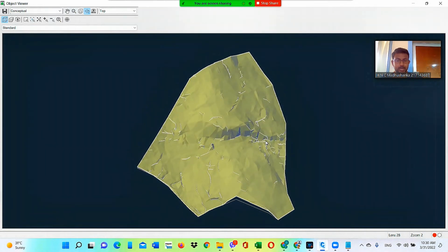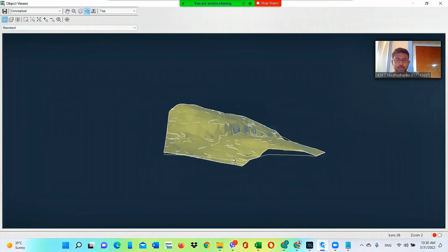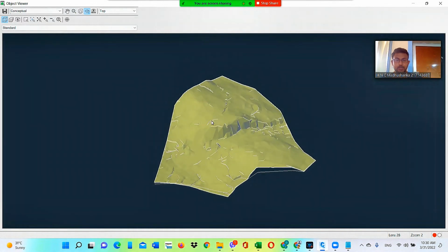And if you want to put a road to go to here, from here you can go almost parallel to the contours by this side and come to the top of the mountain like that and go here, thinking of the gradient. So you can have a small gradient if you go around like that and go parallel to the contours, to the top of the mountain, and again go down like this.